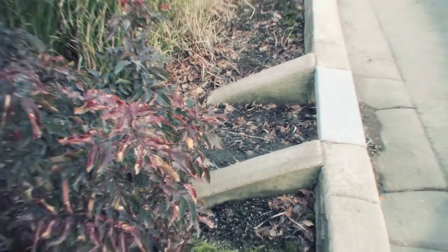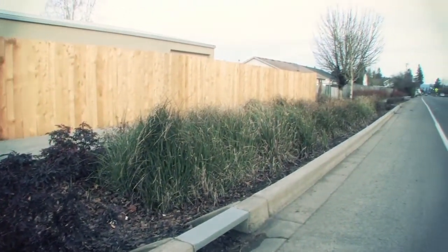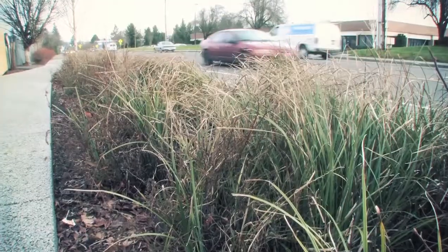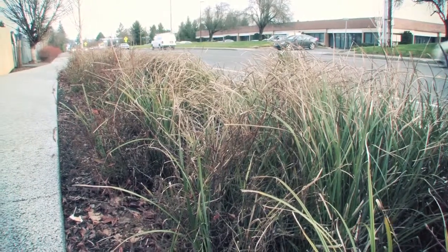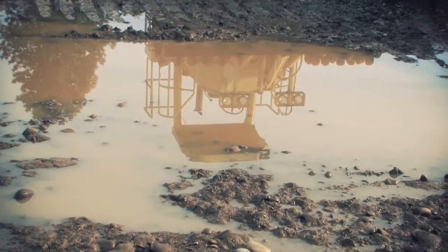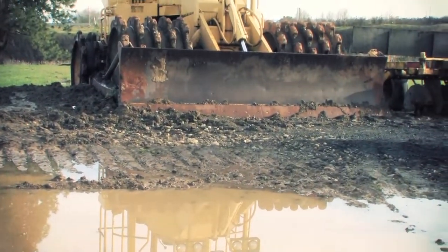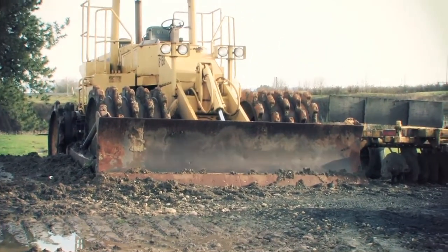Bioretention is usually best used upland from inlets that receive sheet flow from graded areas and at areas that will be excavated. The site must be graded in a manner that minimizes erosive conditions as sheet flow is conveyed to the treatment area, maximizing treatment effectiveness.